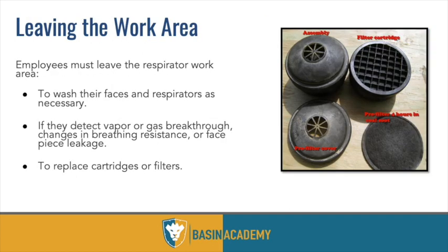If you have to leave a work area where you're wearing your respirator, that's fine. No big deal. The mask is fogging up, you're getting sweaty, you've got to itch your face, whatever. You can do those things, but you must go to the briefing area or the green work zone instead of the red work zone where the contaminant exists prior to doing that. Also, if you have to replace some part of it or it's not sealing properly, etc., you need to do that in a safe area.